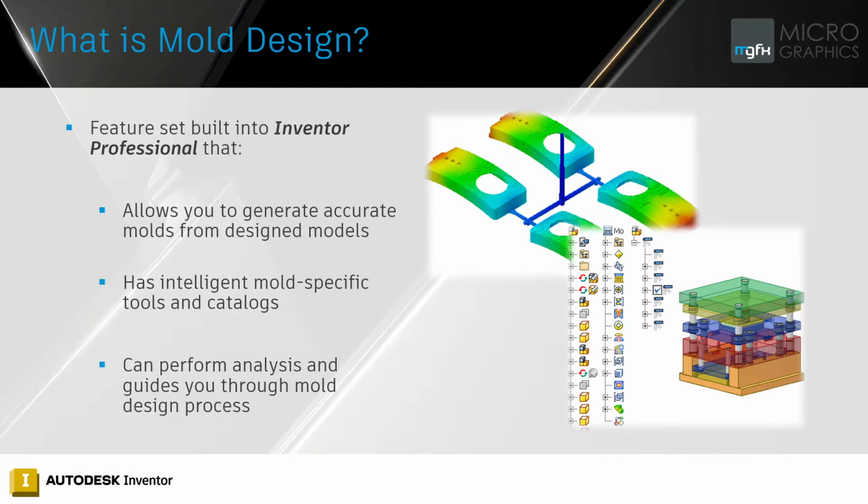So what is mold design? Well, mold design is a feature set built into Inventor Professional that allows you to generate accurate molds from your design models. So you can have your plastic part design in Inventor and immediately take it to a different workspace that will design a mold around it. Nice thing about it is that it has intelligent mold specific tools and catalogs for you to pull out parts. Although there are some caveats to that, and we'll get to that in a second.